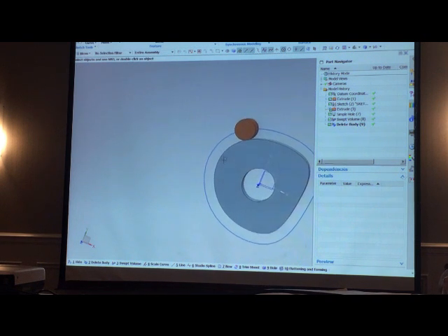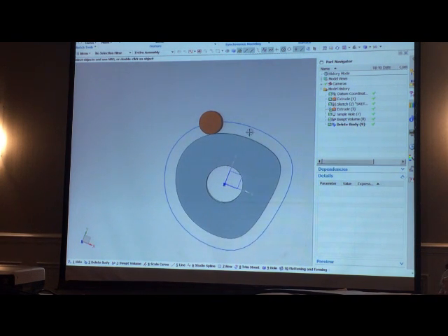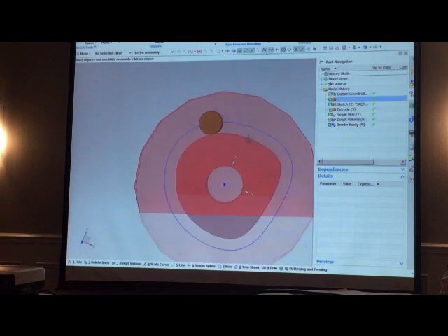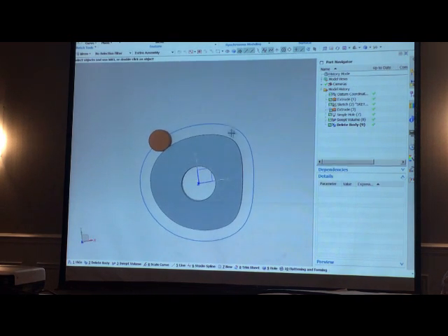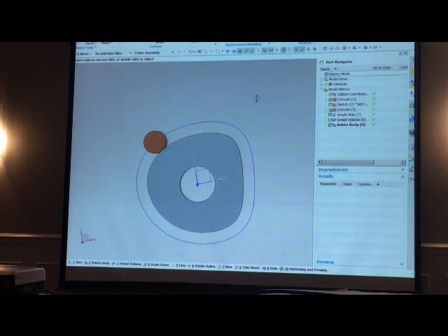Now, this is the true profile of this cam. Somebody said, well, wait a minute, I could have just taken this curve and done an offset curve, the radius of the follower, and I would have had the same result. No, not quite. As it went around this corner here, it actually has a different geometry situation. It'd have been close, but it wouldn't have been exact. This is an exact way of doing it. So this is another use for this ability to take a piece of geometry and move it through space and have it give this model.